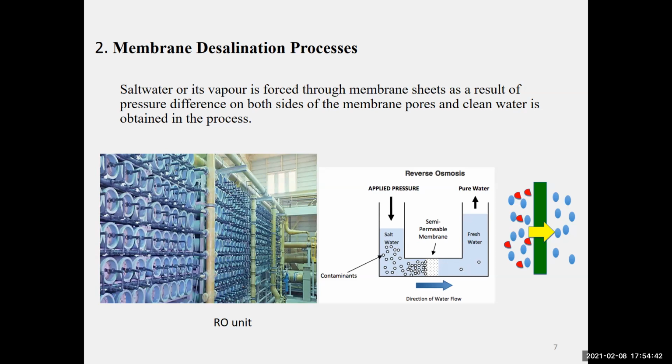But we don't want that. We want the opposite to occur. So what's keeping this kind of continuous motion is the osmosis effect of the two streams, the two solutions. So we have to apply a pressure which is higher than the osmotic pressure for the sweet water molecules to leave through the membranes and go to the other side, and then you can collect fresh water. In other words, you can convert part of the salty water into fresh water by passing almost pure water in, leaving the salty water or the high concentration behind.